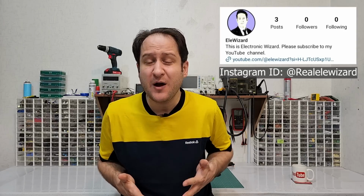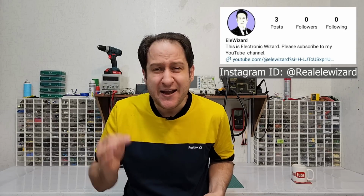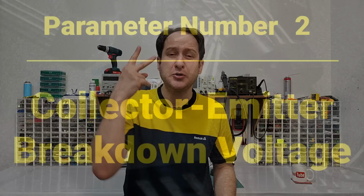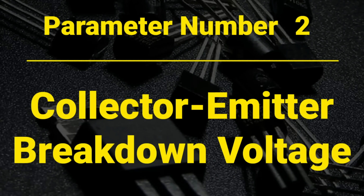What about a 500 volt DC motor? Can any transistor switch any voltage, you may ask? To answer this question, I have to move on to the next parameter. Parameter number 2, collector emitter breakdown voltage. VCEO is one of the most important parameters of any bipolar junction transistor. It indicates the maximum voltage the transistor can withstand on its collector emitter junction.